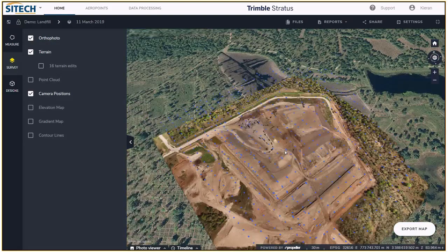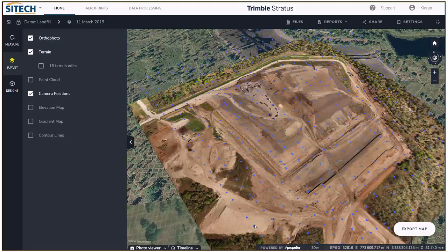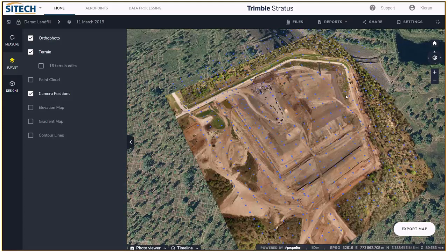But essentially, for those who aren't as familiar, we've got a drone with a screen on it. We've said, hey, here's the extent of my site. I've put some settings in and it's gone and flown along and taken a photo every couple of seconds, I think that is, every 1 or 2 seconds, something like that. And that might have taken 2 flights, 25 minutes maybe. And afterwards that's done, we've got all the photos, and hopefully we'll have some ground control. No, not in this one. Anyway, we would have a CSV out of our rover that we've been given.